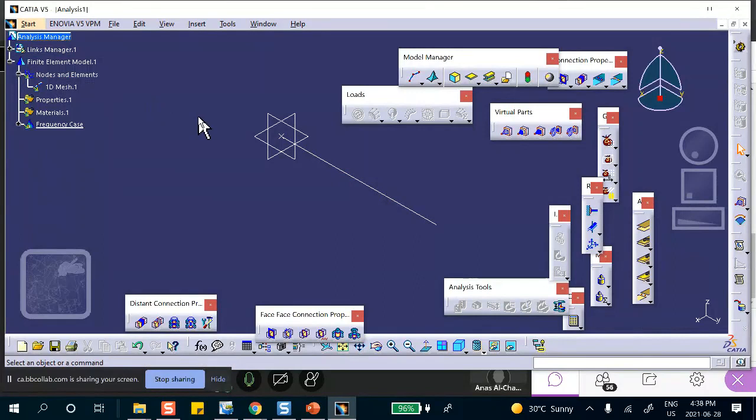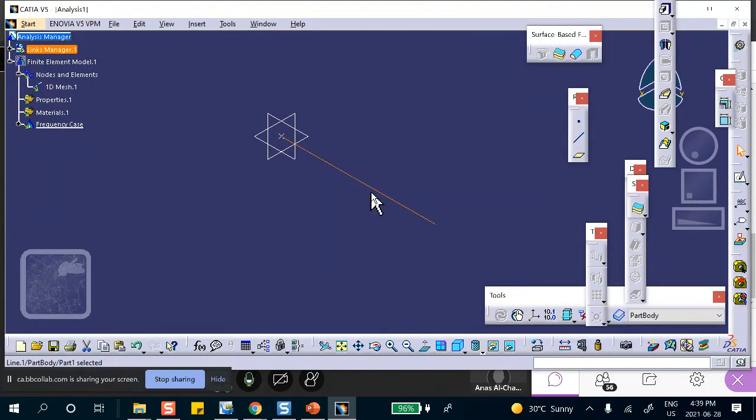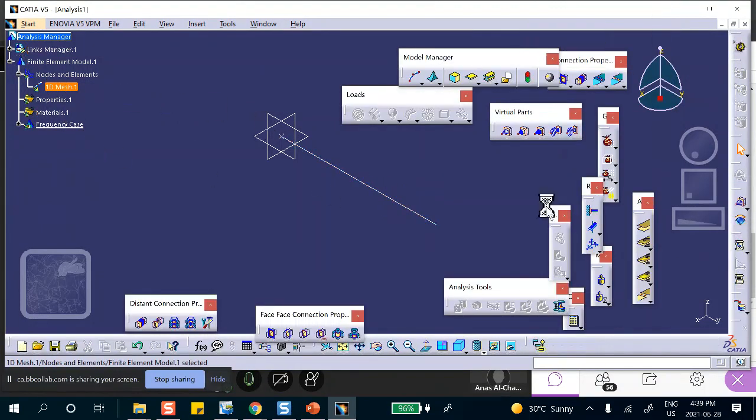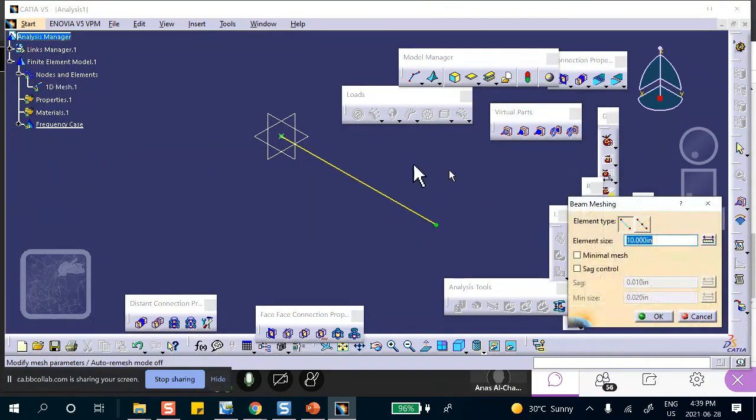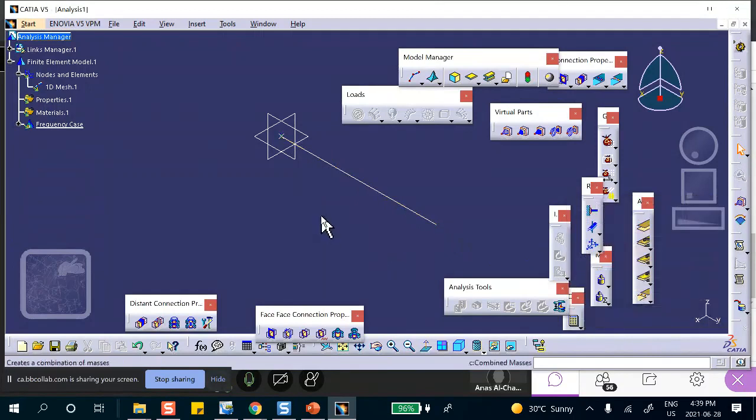Professor, you just made the element size 10 inches. Oh, really? So it's 1 element. Believe me, it's still going to give me a good result. Let's go back, fix it. Sounds good. Okay, let's make it 1. These beam elements are so robust, you can get excellent results with 2 or 3 elements through the length. Even in some cases, 1 element. But it's all right. I made it 1 now.